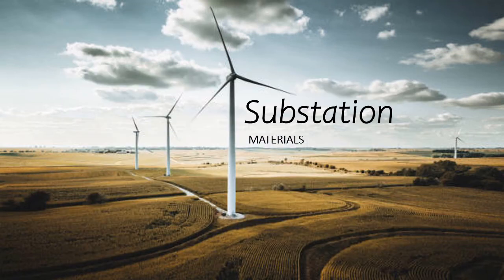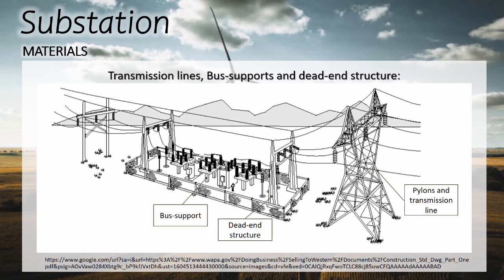Next, we will look at the materials that will be used in a substation. Steel pylons carry high voltage transmission lines made of aluminium. These lines are received by a dead-end structure in the substation. Other components in the substation are supported by bus supports. Dead-end structures and bus supports are made of galvanized steel for high strength and to prevent corrosion. Sound rocks are laid on the surface because they have high resistivity and keep wildlife away.